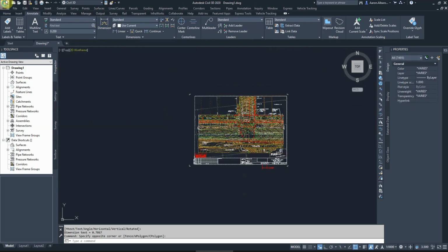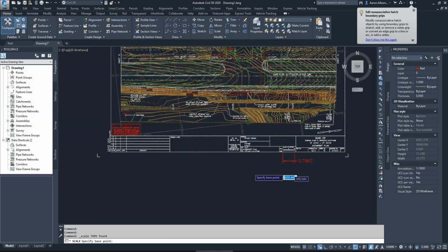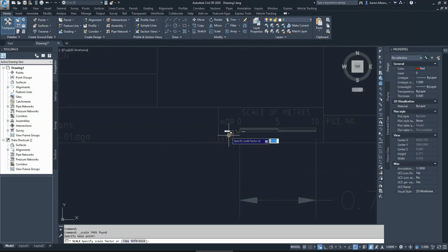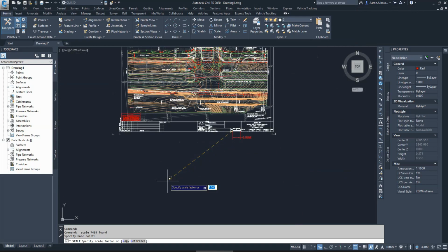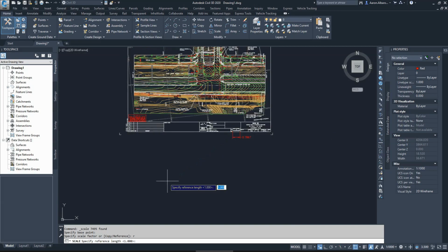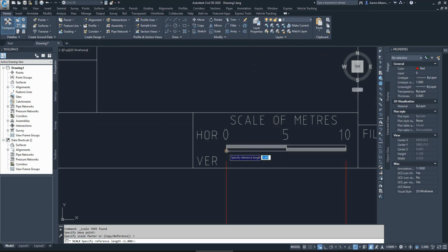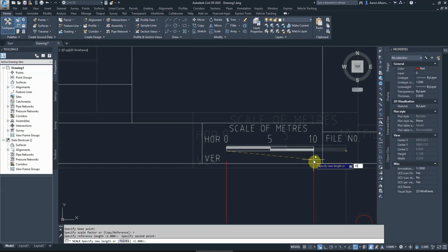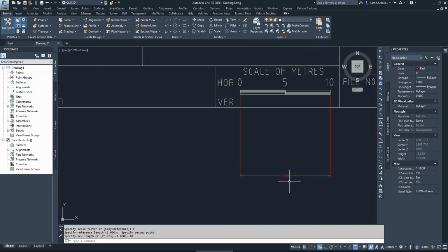All we have to do is select this drawing. Again, I will do it. So I will go to Scale under the Home button, and I usually scale from this point here. Zoom in so you can make sure you got the right point, and it's asking me for the scale reference. I'll put R to enter the reference, enter, and I say from this point to that point I want it to be 10 meters. And that's again 10 meters, as you can see.